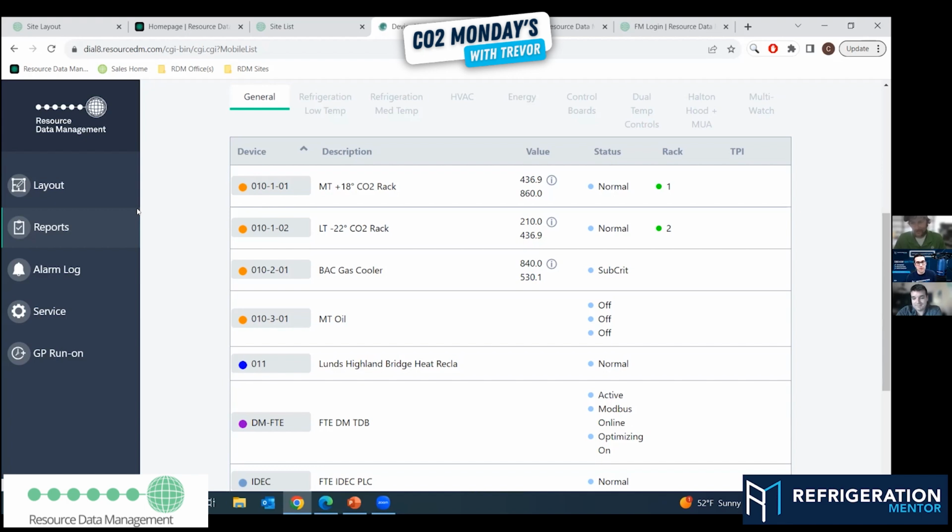And this is another thing that I've learned. You have a controller that'll do 3 valves, one controller that'll do 3 valves for a case, for example. But those different coils may be set up differently. Have you noticed this, Cody? Because I've had guys say, I took the program, I jammed it in all the cases because we know it's on the same rack, we know it's the same suction. But even in that one case, you could have different pressures. Maybe it's a design by the OEM. Maybe the airflow across that coil is different on the one on the end than the one in the middle. So if you just put the exact same parameters in, you might not be getting the most efficient running case.